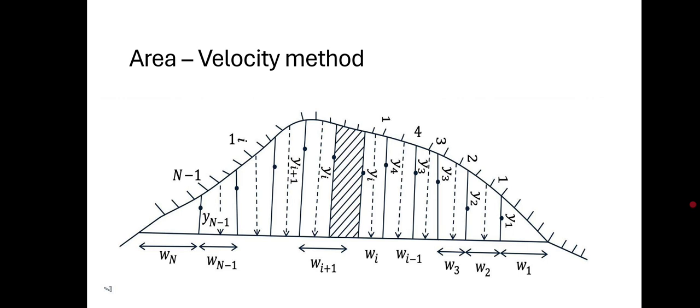When the meter is lowered in water and faces the current of water in the channel, the wheel rotates. The rate of rotation of the wheel depends on the velocity of flow. The number of rotations of the current meter cup wheel for various velocities are noted. Then we move on to the area velocity method.